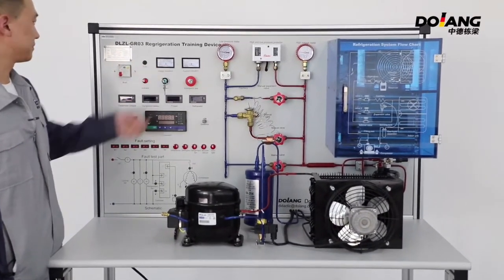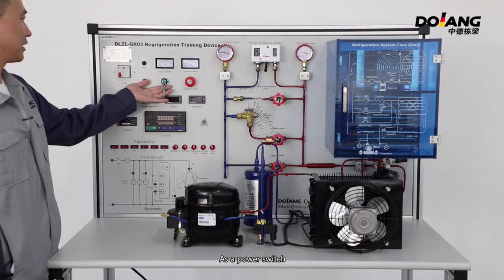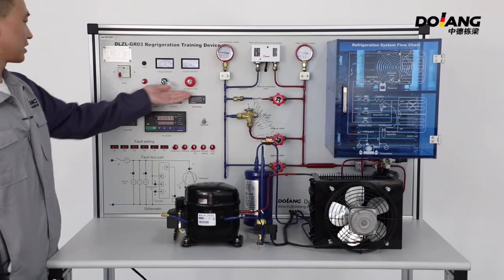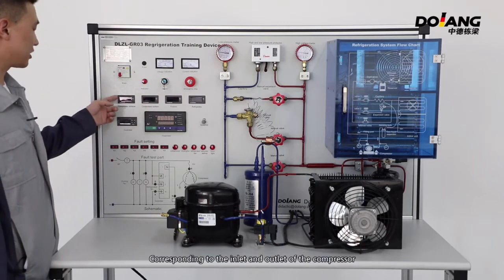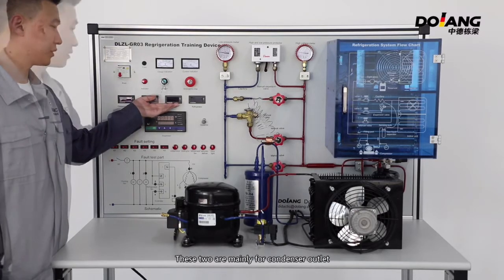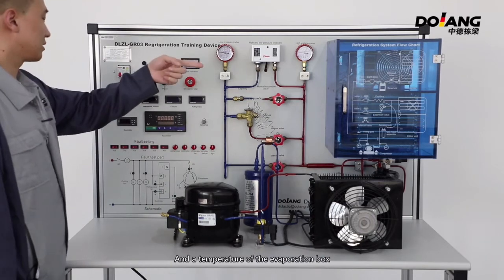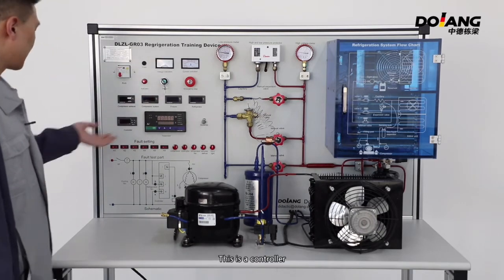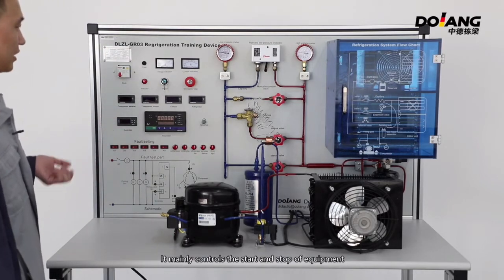This is the voltmeter and this is the ammeter. This is a power indicator, this is a key switch. This is an emergency stop. This is for our thermometer, corresponding to the inlet and outlet of the compressor. These two are mainly for the condenser outlet and the temperature of the evaporation box. This is a controller. It manually controls the start and stop of the equipment and protects the compressor.